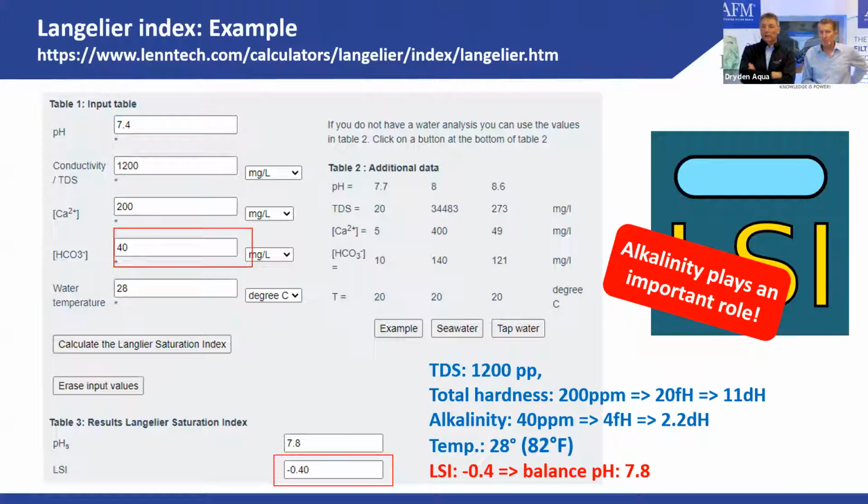This hydrolysis system, we usually run between 7.4 and 7.6. We know that chlorine works better at a lower pH. Free radicals don't care about the pH, but because of the corrosion risk, we would go a little bit higher and we would increase alkalinity. So really alkalinity is the main driver.